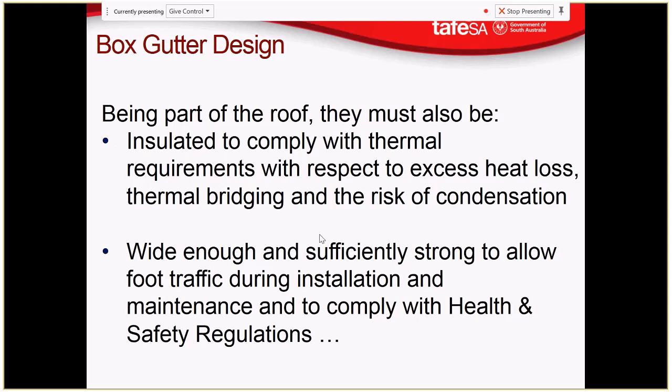They have to be wide enough and sufficiently strong to allow foot traffic during installation and maintenance, and comply with health and safety regulations. So the box gutters need to be supported in their base, in the pan underneath. We'll see that.